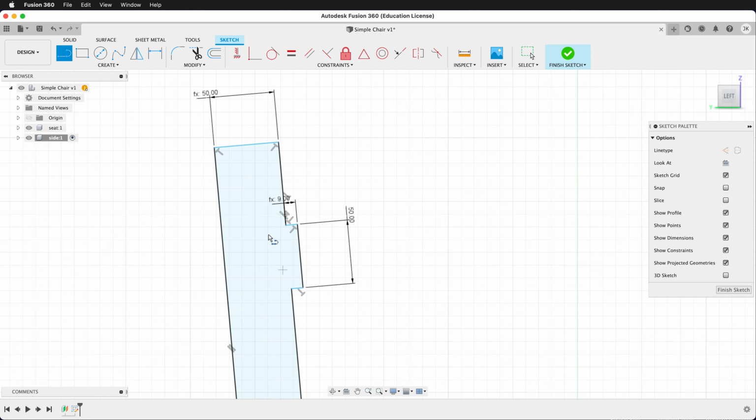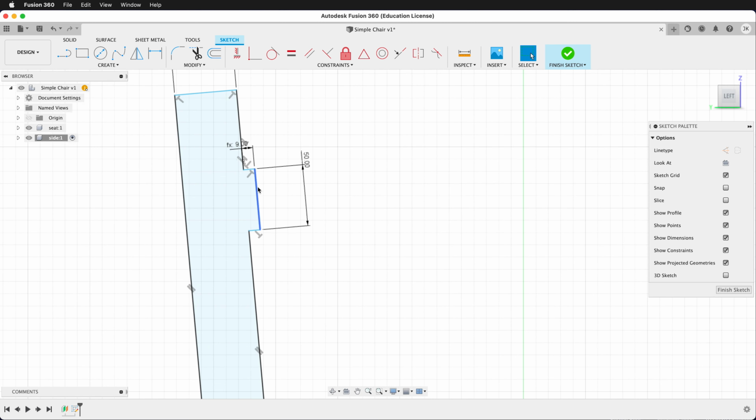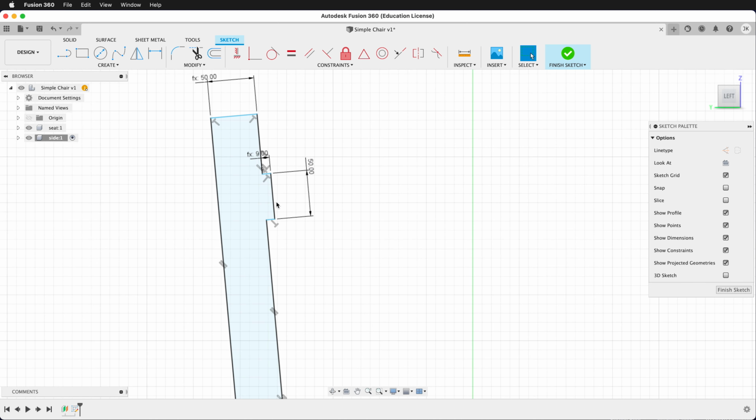Now let's go up here and see how we can define all of these pieces. We need to make this piece centered where it wants to be. So we know we have the backrest height, which is approximately 200, but I want the backrest to be sitting up ply. So what I can do is define this dimension here. I can call it backrest minus 50. So I want it centered on the backrest divided by 2. And then I can just take off a ply. And so that will put that centered right on the backrest.